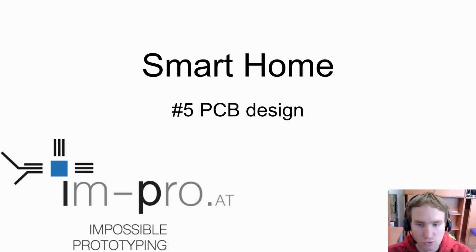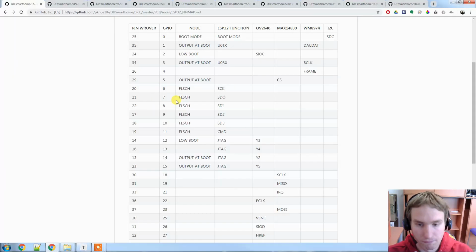In this video, we want to talk about the PCB design. First, pin mapping. As I told before in some videos, when we chose the microcontroller, I was thinking the ESP32 has enough resources. It turns out that some ports are already taken for the flash and the PSRAM. So yeah, we actually run into resource problems.